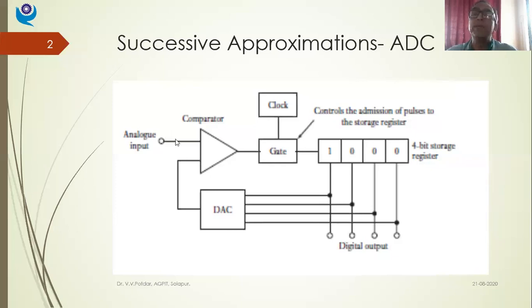Now, what is the input signal? Input signal is 8 volts. What is the feedback signal? It is 7.5. Okay, so in this cycle, the gate will still not allow the signal from the op-amp. Till what time? Till then, I'll keep on generating the digital signal: 7.5 volts, 7.6 volts, 7.8 volts, 7.9 volts. Accordingly, this signal will be fed here and will be constantly compared with the input analog signal. Presently, as I said, it is 8.